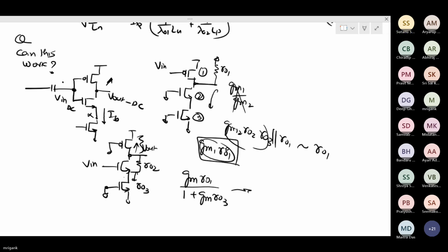Yes, sir. So in case you are having capacitive coupling, you can't even solve for Vin. It's a floating node. It will be determined by some random value based on the gate leakage, source leakage, whatever. It is not solvable. Ultimately, in the actual circuit, it will acquire some value based on the leakage current.